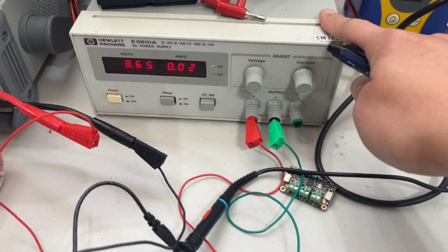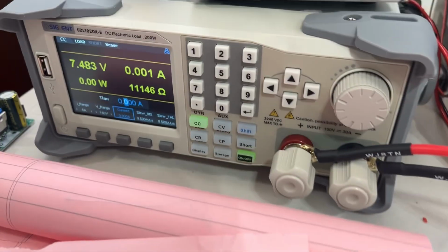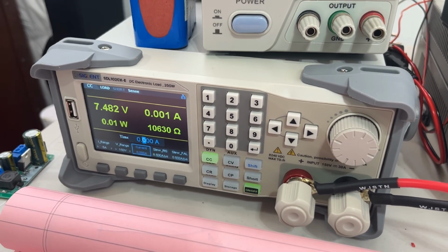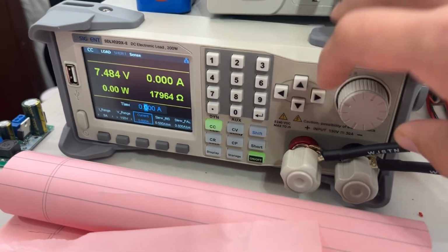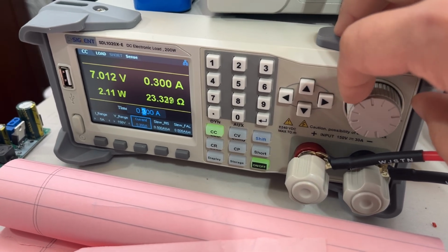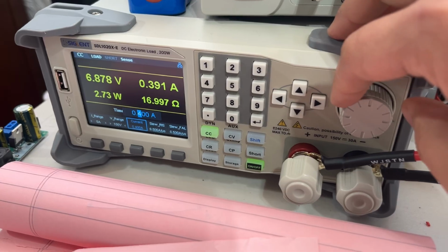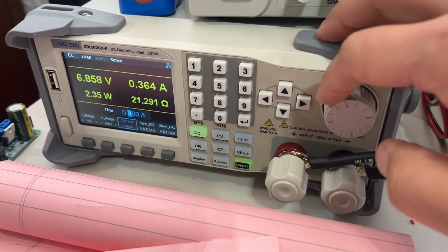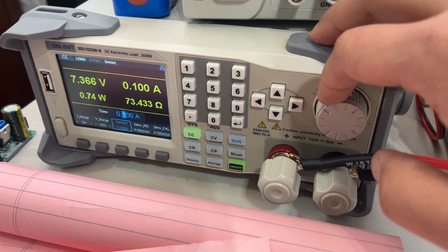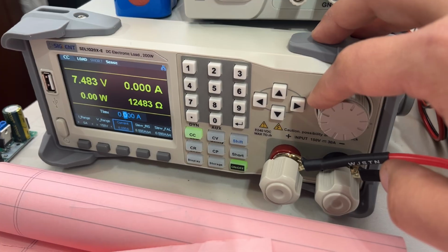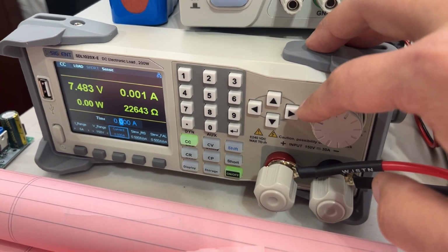And this is the power supply. It's at about 8 volts, and then over here is my DC load. So the DC load here, this is standing in for the charge controller, and why it's useful is that I can turn this knob and it adjusts the current draw. So imagine this were the charge controller and it was drawing 0.4 amps, and it tells me the voltage that the charge controller would see at this level. And as you can see, at 0 amps being drawn, I'm at the open circuit voltage, it's like 7.5 volts for this simulated panel.